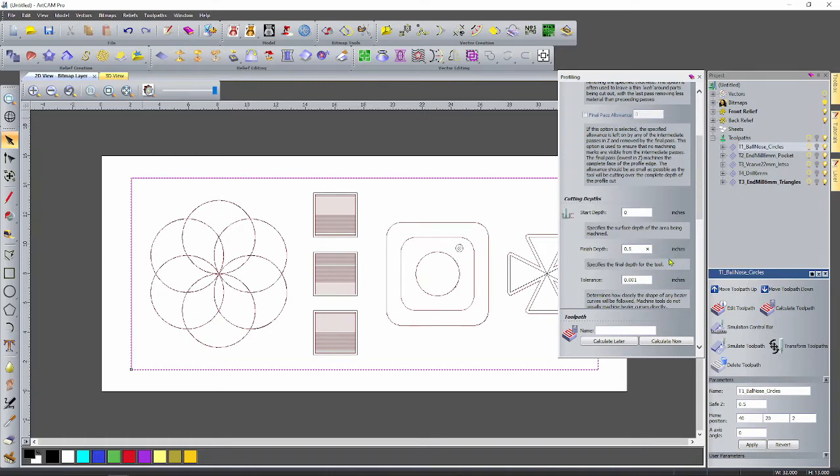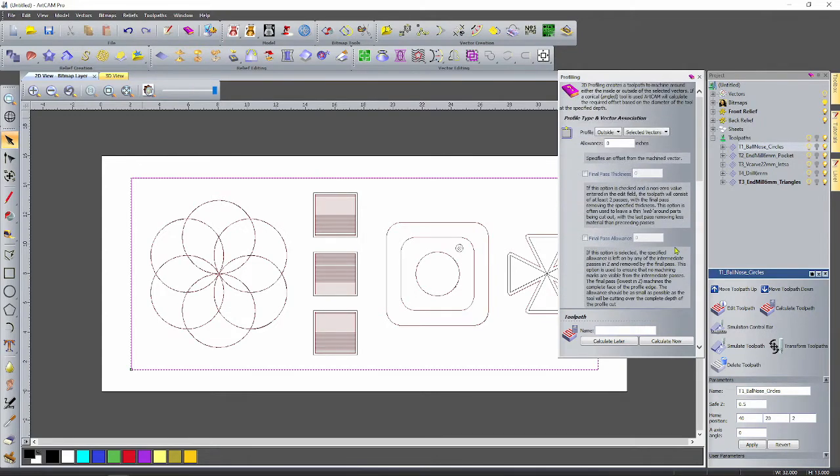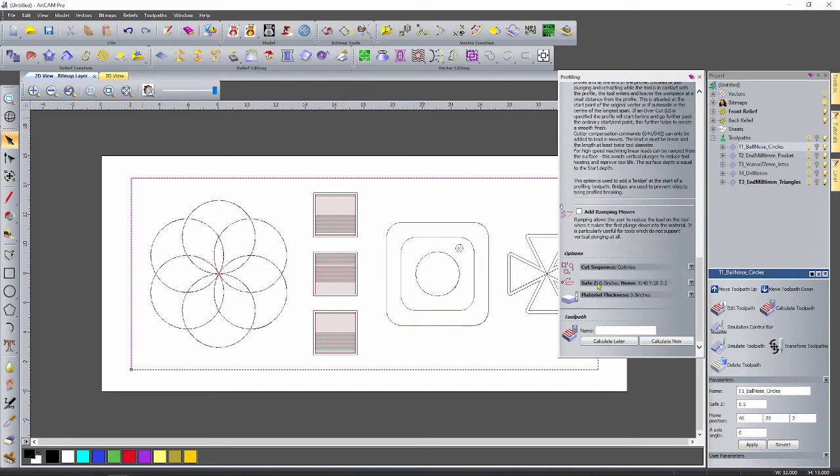Material is 1/2 inch, so let's go a little bit deeper to make sure that it's gonna cut it out. It's not gonna damage my bed, the CNC's bed, because I have something underneath. I mean, between my actual workpiece and the table. That should be fine. Yeah. Give it a name. T2 end mill.